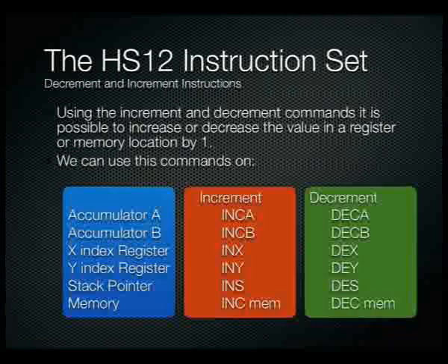So like before, we have the same notation as before. If it's INC, it refers to 8-bit. If it's INX, it refers to 16-bit sort of memory size. So where we have increment, we also have the decrement. So we have DEC A, DEC B, DEX, DEY, DES, and DEC memory as well.